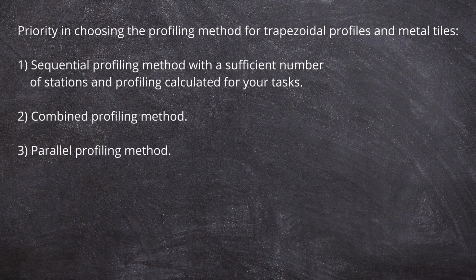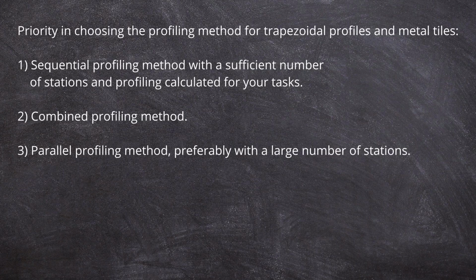And if the supplier does offer you a parallel method, make sure that there are enough stands to minimize the negative effect of metal sliding to the side. I think that depending on the complexity of the profile, it could be from 15 to 23 stands.